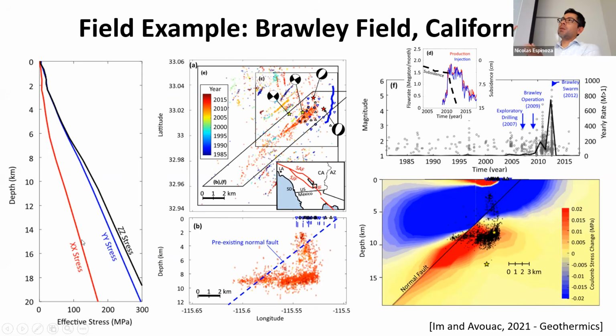And since the minimum horizontal stress might be already close to the failure limit, changing that a little bit will make it easier to reactivate those normal faults. The opposite would be reverse faulting, because your vertical stress is more or less constant, and you are decreasing your horizontal stress, but those already are pretty high. So you might actually be getting some of these systems into safer conditions from the point of view of shear.